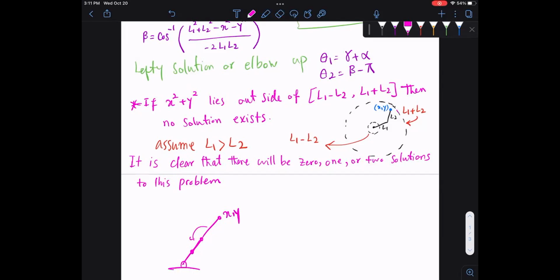So the reach of the robot is important to know in advance. You have to think about it: what if I'm following a trajectory and it falls beyond my reach? What does the robot have to do? It can't just freeze. You can say, hey, maybe go to the closest point. So it just travels to the closest point to create a smooth trajectory. Does that make sense?